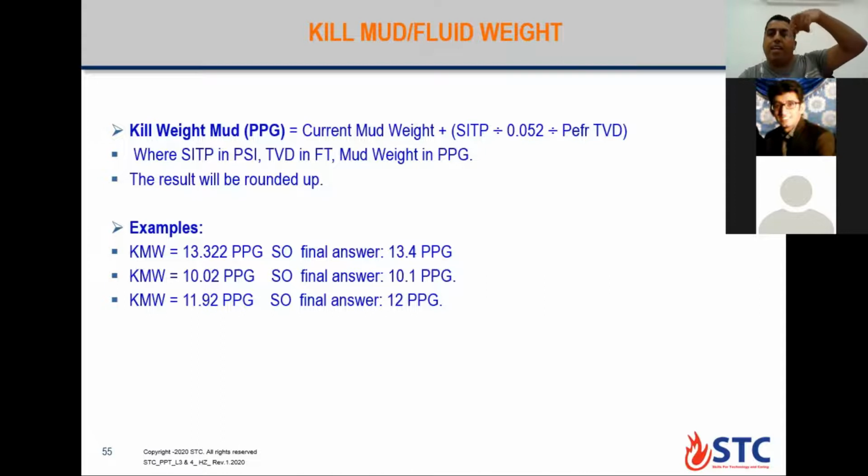Or you can mill, make a clean out for any restriction inside the tubing, get the restriction free. Then you displace the brine inside the tubing with coiled tubing. So you kill the well with coiled tubing, with circulation. Okay, fine. Thank you.